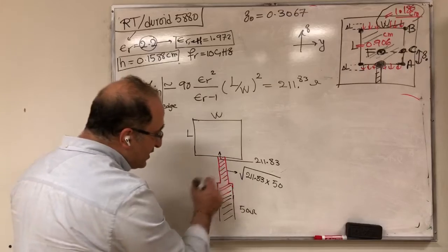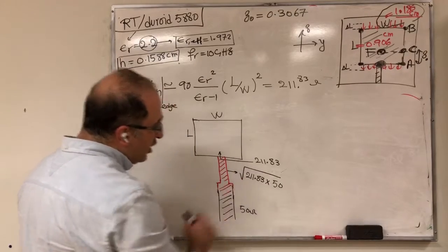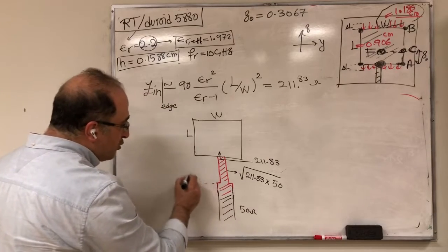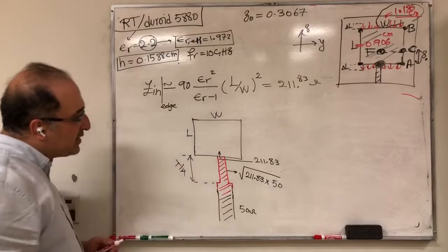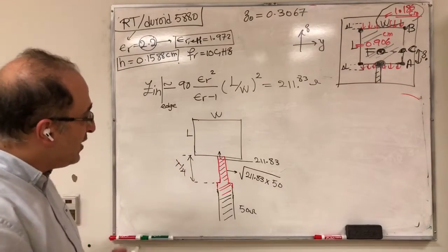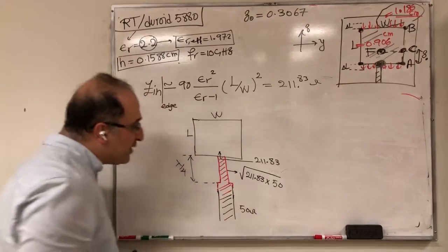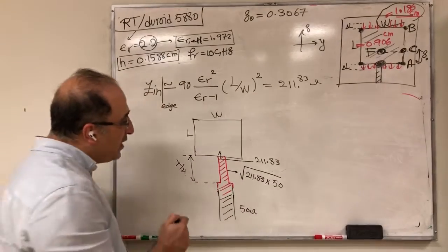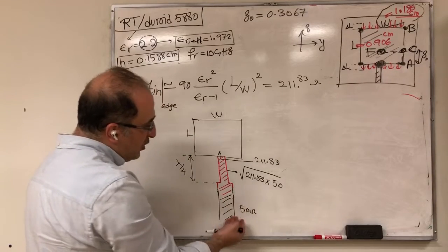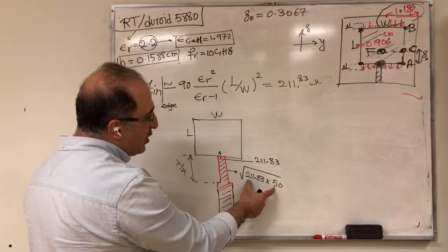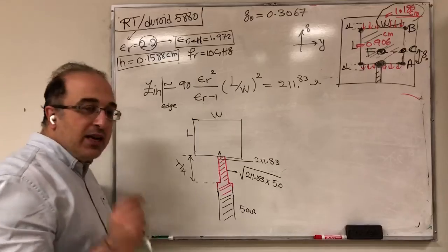So the characteristic impedance of this line would be the geometrical average of these two, and it's also a quarter wavelength in terms of its length. So this is the way that I'm matching it. And now the reason that I plotted this a little bit thinner is that, as you will see, when the characteristic impedance becomes larger, which in this case is definitely the result of this square root being larger than 50, then the width becomes smaller.